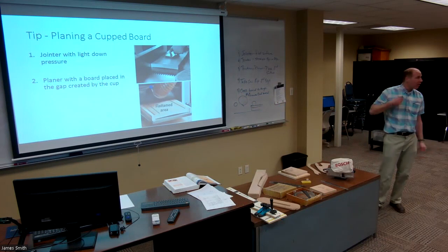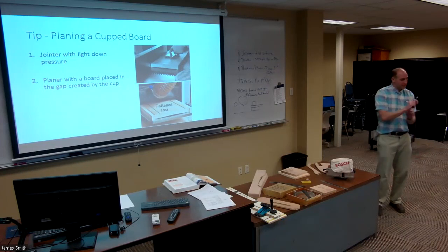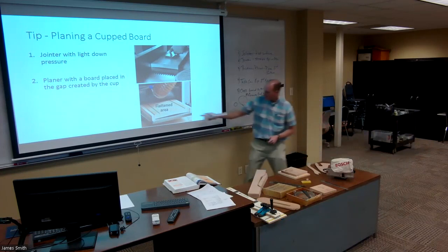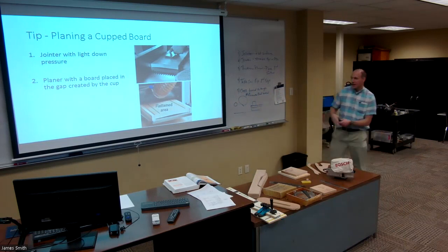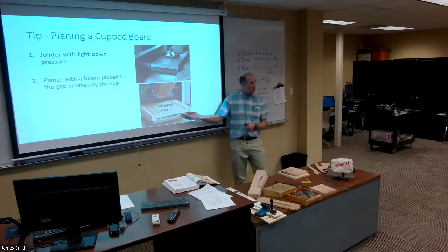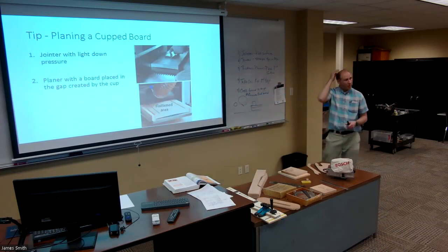They talked about how sometimes if the cup isn't so severe, you can get cups out by using a surface planer. The other trick I've found is to take a little thin strip of soap or a strip of wood, and you can glue it to the bottom or use a piece of two-sided tape to keep that cup from getting pushed out when it goes under the pressure roller. And that will help to support it. You're able to cut off a smooth top surface that's flat.